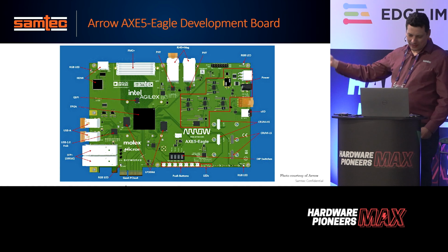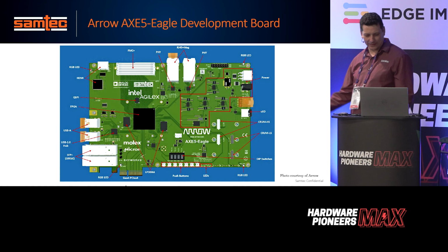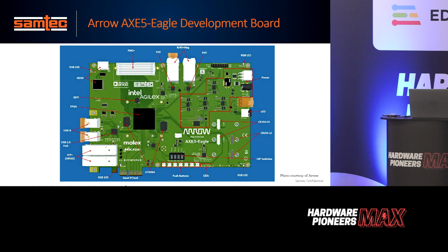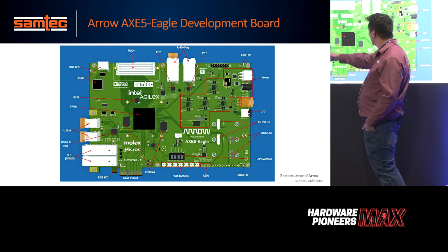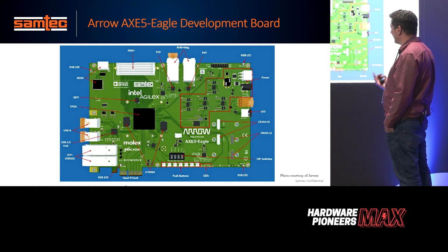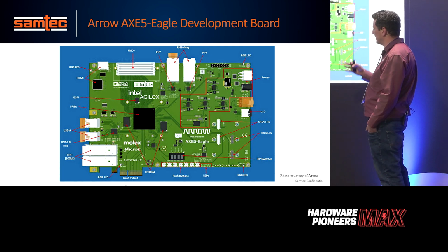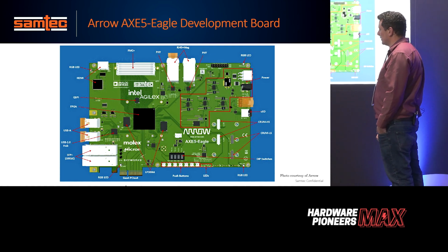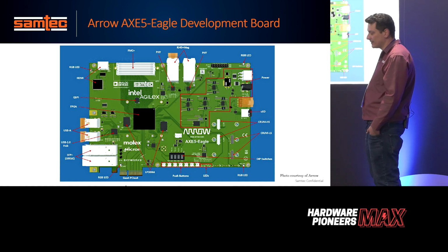So if we look at the typical FPGA evaluation kits, this is a good example from our friends from Arrow, where they did this evaluation kit for Intel. And in here you can see a lot of I/O, so you can go directly at high speeds to optical transceivers from here. You can do video signals over USB, for example, if you wanted to. But the important thing is adding these add-on cards to get the functionality. So if you want to connect your FPGA with an analog-to-digital converter, for example, to get some JESD signals into the FPGA to see the link is working.